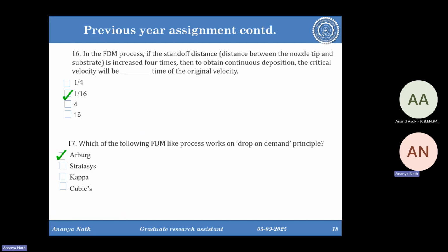It's 1/16. It's inversely proportional. Because when you increase the standoff distance, to get the same deposition, you need to decrease the velocity. So it should be 1/16.